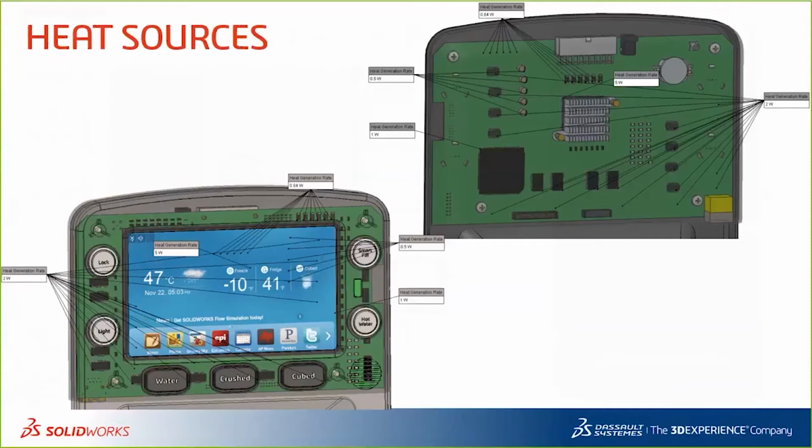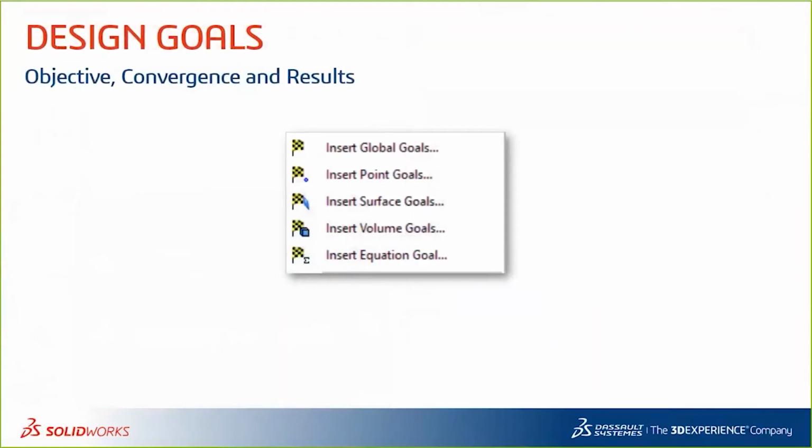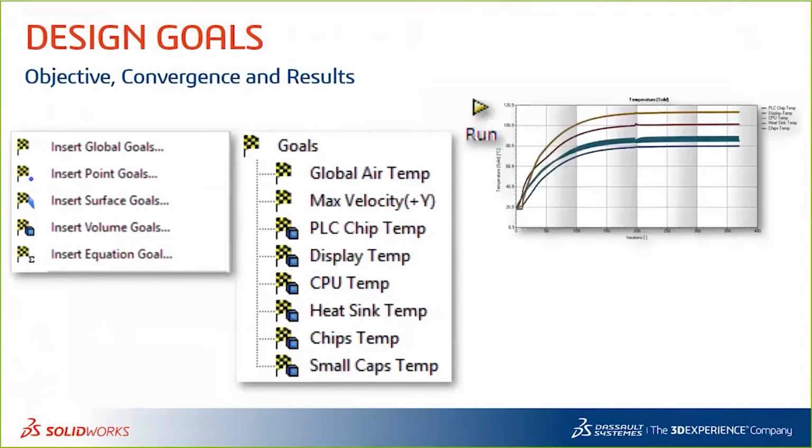So this panel, if you look in the back of this panel, the PCB, there's quite a bit involved. There are many components, many chips, and we can see in this image all these different components on the PCB generate some form of heat. So we need to account for all these different heat sources. We can set all this up within SolidWorks Flow Simulation.